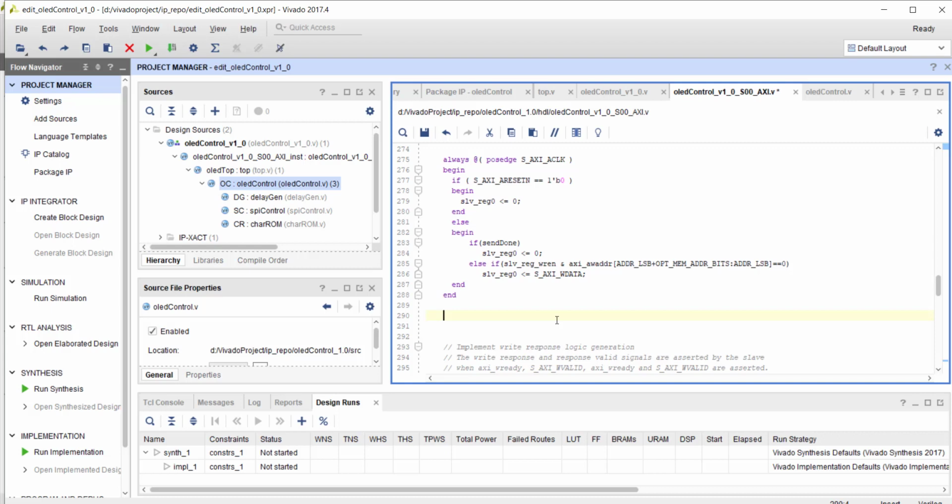Now the processor should clear that bit. Using software, you should make that bit 0 before sending the next data. Otherwise, that bit will remain there forever, and when the processor tries to send data, immediately he will find like the data has been sent, but actually it is not. Okay, so the status will be set by hardware and cleared by software, just the opposite of control register.